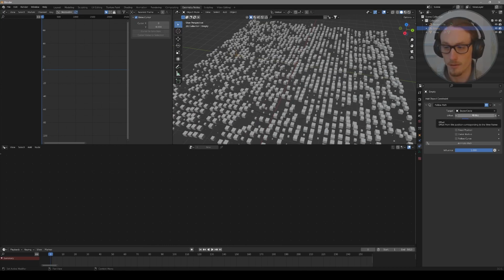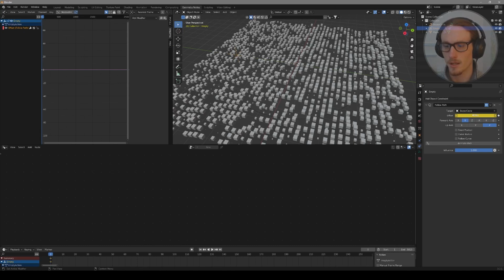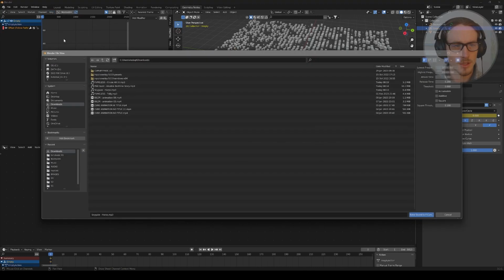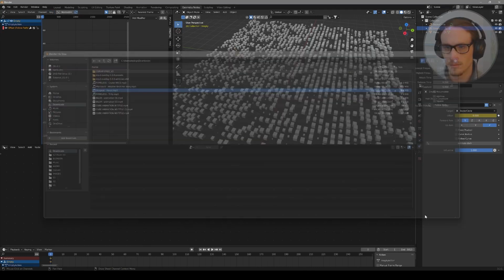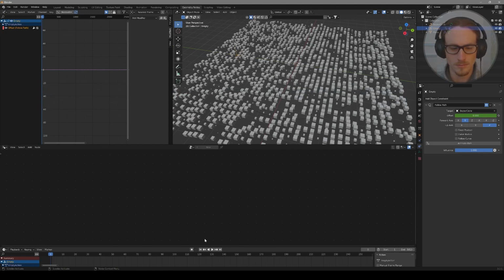As simple as hovering over offset, press I. We're at keyframe 0, keep in mind. I've got the plane axis selected, offset, go to key in my graph editor, bake sound to F curves. Bake.